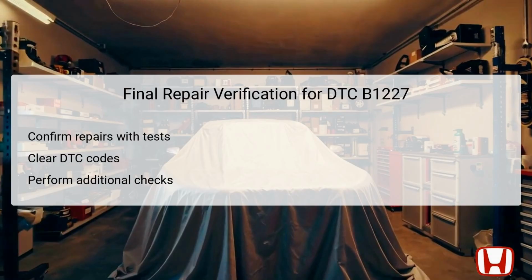After proceeding through the troubleshooting steps and making any necessary repairs, it is essential to verify that the repairs have resolved the issue related to DTC B1227. Start by confirming the functionalities through tests to ensure that both the outside air temperature sensor and the climate control unit are operational.